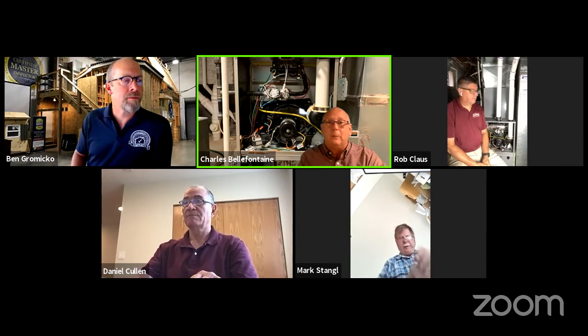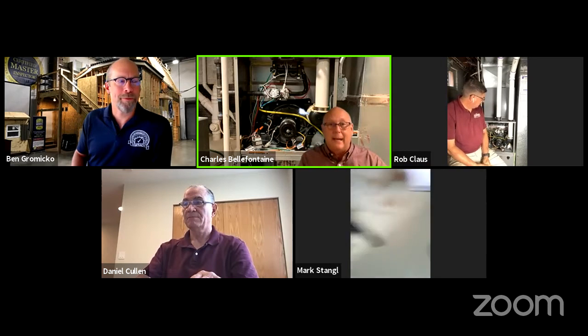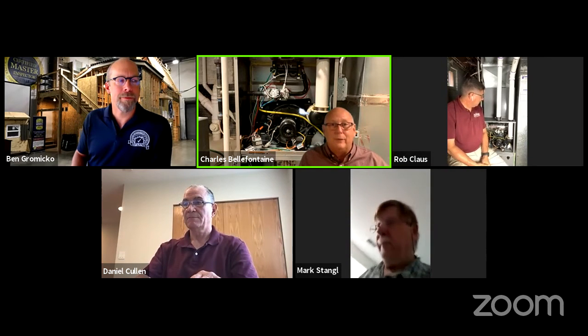Number 2 is going to be the heat exchanger itself. So we're going to have the fire inside the metal box, inside the heat exchanger. We're going to blow air outside the heat exchanger. As long as all that's intact, then there's no way for the carbon monoxide, again, to get into the circulation air. And then the third safety feature is going to be our pressure differentials.